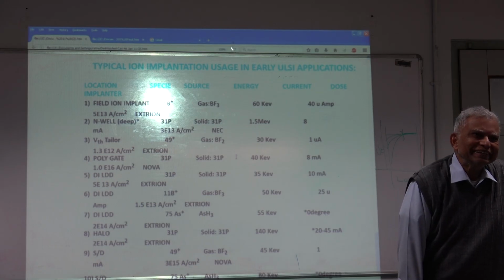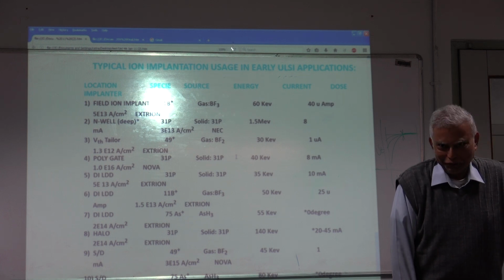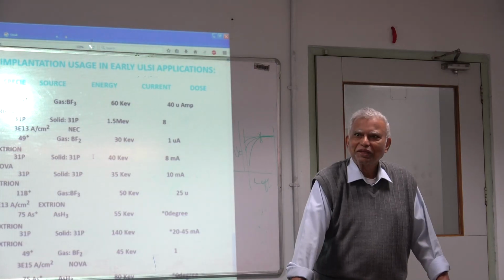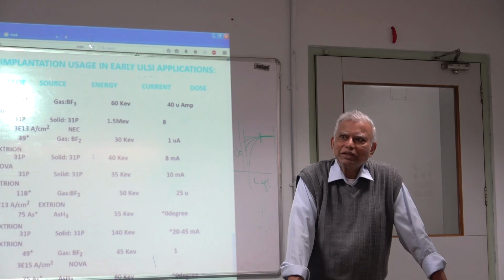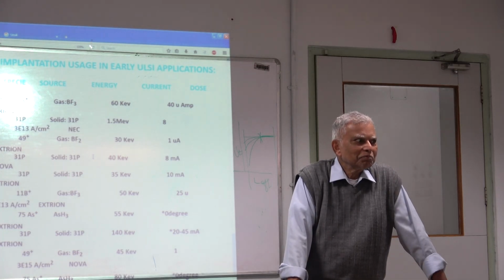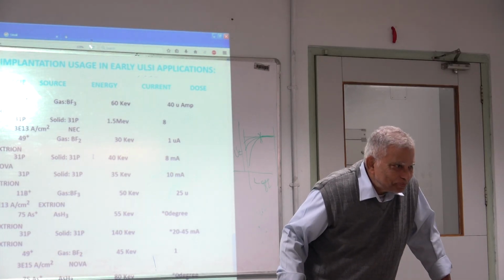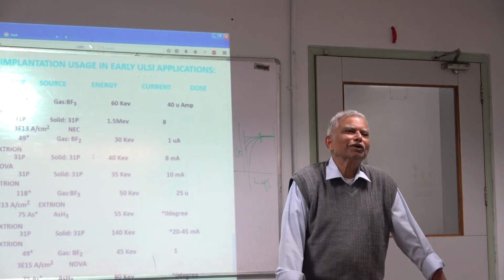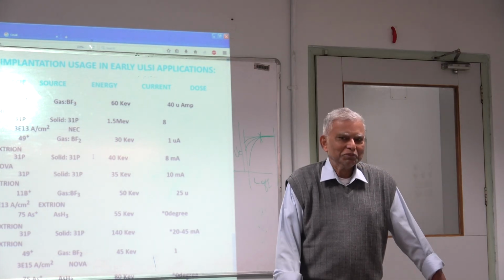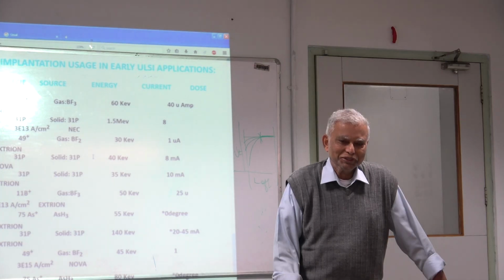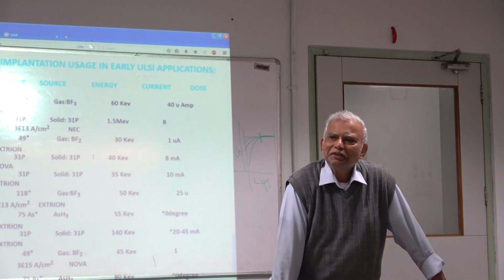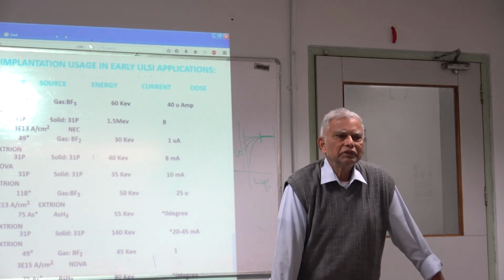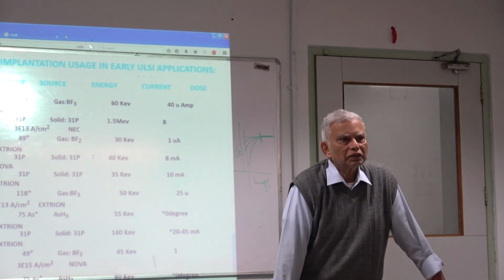Then the question of thermal budget comes in. Because we are limited in thermal budget, which is very precious, we have to allocate them very precisely. So we want to clean up the mess we created by putting the impurities in silicon, but we want to do that with least amount of thermal energy. And that happens to be the name of the game in integrating technology. How we integrate the technology so that we could recover those damages, but put the least amount of thermal budget into the entire way of doing the integration. And that has been one of the major challenges of technology integration when you scale the technology.